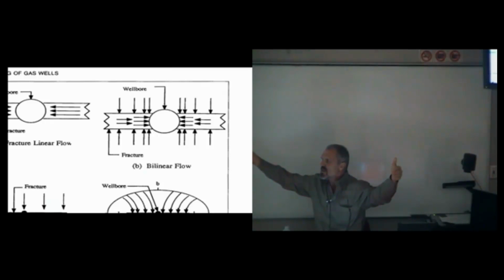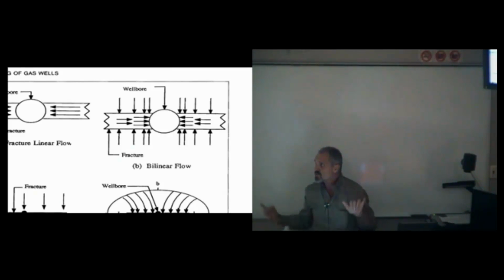Once there's actually flow from the fracture tips, then you have this pure formation linear flow, and you're done with bilinear flow. But that period of time is greatly extended compared to that predicted by Cinco-Ley, because his work was single phase, because it was analytic solutions. In the simulators that we run, we now actually fill our reservoir, our frac, with water, pump the typical amount that goes in, flow back the water, and we see that it takes a lot longer to get out of bilinear flow.